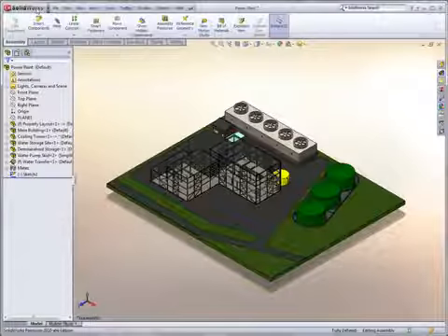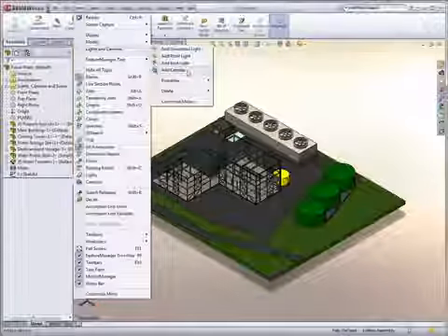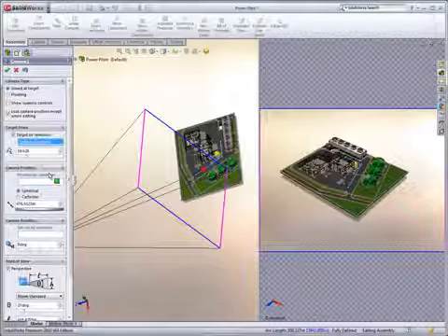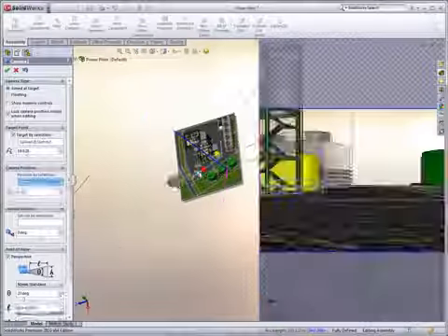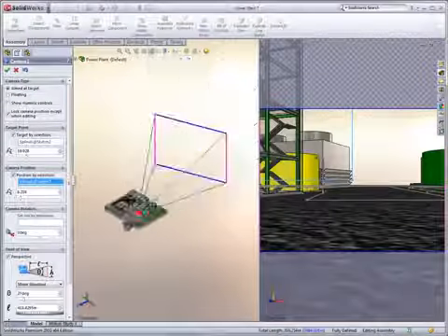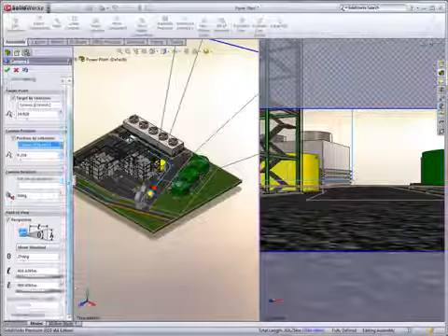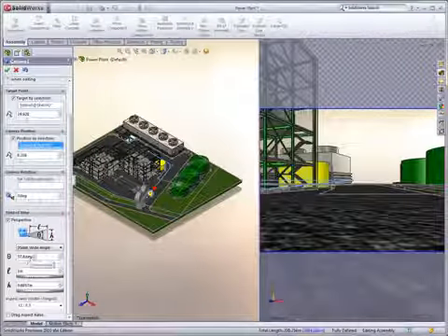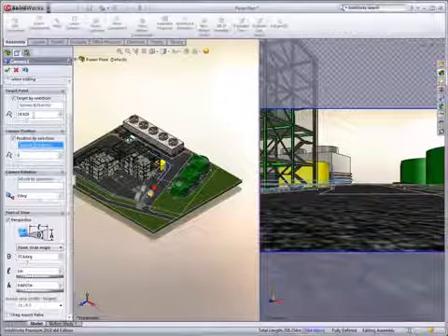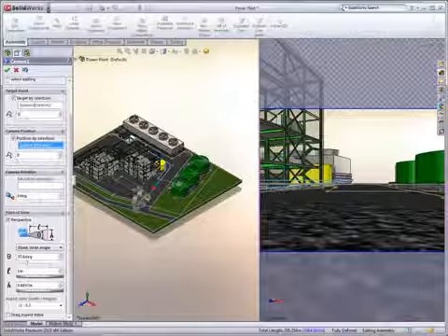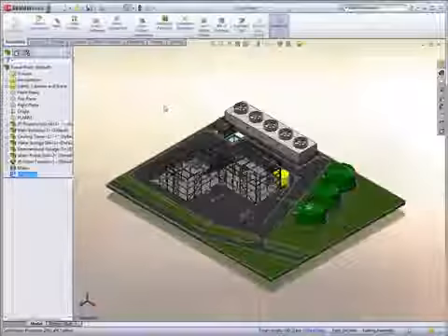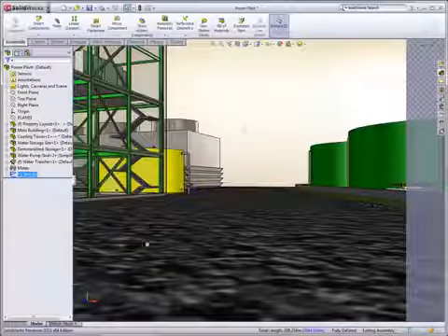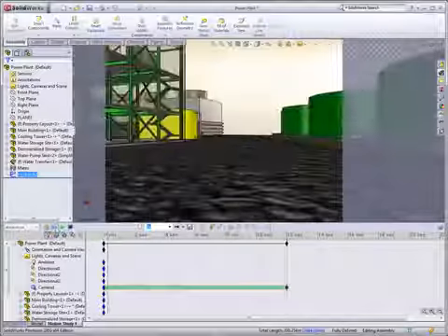Finally, sharing our designs with our customers can really get an idea across. One method is with a walkthrough or similar animation showing the details of our design. Typically a complicated task, SolidWorks handles this with its easy-to-do approach. Simply giving the software a path to walk along, setting a camera with the appropriate control to that path, and a timeline are all SolidWorks needs to generate detailed walkthrough animations. From there, we simply need to play the animation.